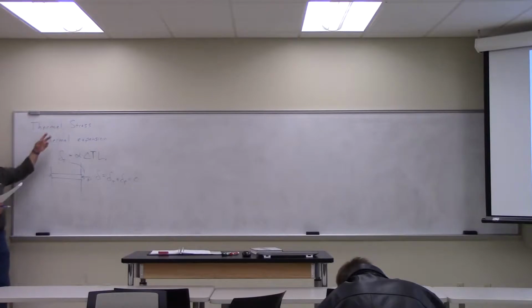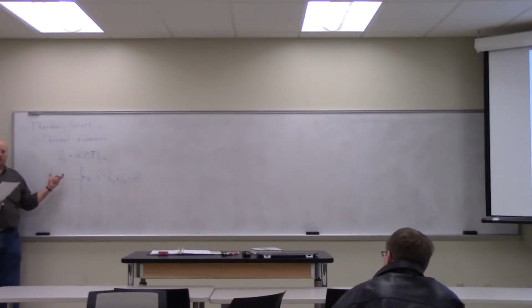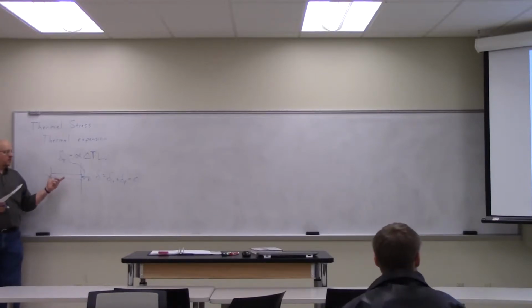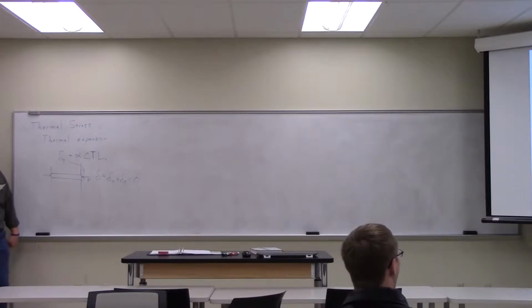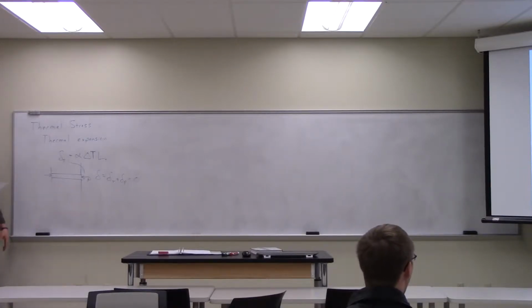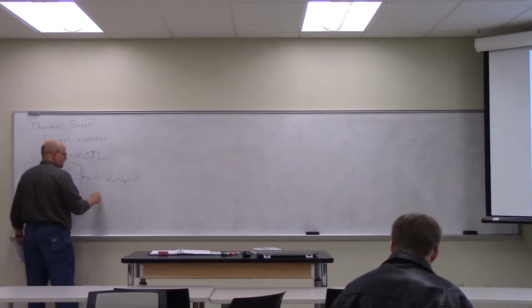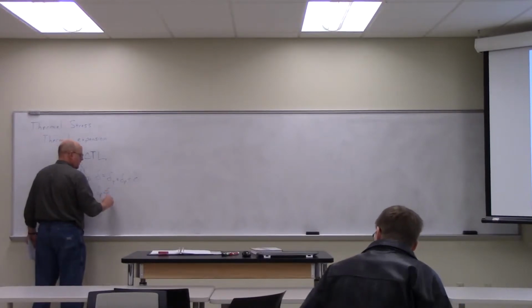So this is what I'm saying, the thermal stress is actually not applied thermally. This delta P is what's actually stressing the bar. The bar is stressed because there's a load. Okay, there's not a thermal stress, but it's thermally induced because of the constraint. Okay, does that make sense? And so in that case, delta P is just going to be equal to minus delta sub T.